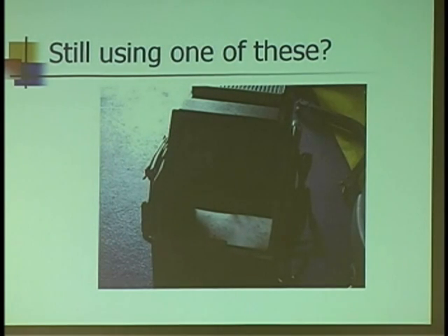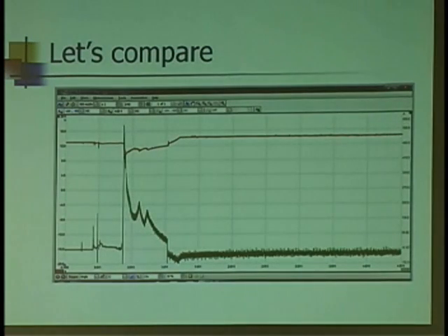Remember I said earlier about keeping your scope fired up on your workbench and doing something nice for your customers? Well, how about a 5-second battery starting charging system test that you can print out and share with them and show them what kind of condition it's in? Not so much for us down south, but I know you guys can have a battery that works just fine on Monday and won't do worth the crap on Tuesday, especially with the colder weather, right? So all I'm going to do is hook my scope up to the battery voltage, positive and negative, and throw a high amp clamp on one of the cables.